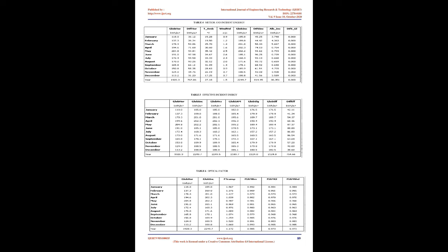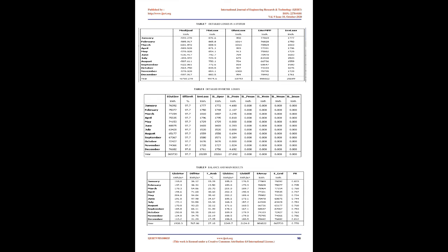The new tool, string mismatch in detailed losses, provides a pedagogic description of the principles of different mismatch modes. This shows namely that the current mismatch within a string is very important, because the current in the whole string is governed by the current in the weakest string, while the voltage mismatch between strings has much lower effects. Power loss at MPP, 0.1%.